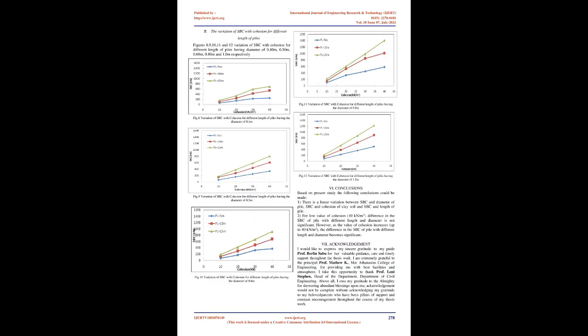Safe bearing capacity of pile. The safe bearing capacity, SBC, of piles could be determined from the load displacement graphs of piles and as per the guidelines specified in BIS. According to this code of practice, the safe vertical load on single pile for initial test shall be least of the following. A. Piles up to and including 600 mm diameter. One, 2/3 of final load at which the total displacement attains a value of 12 mm.